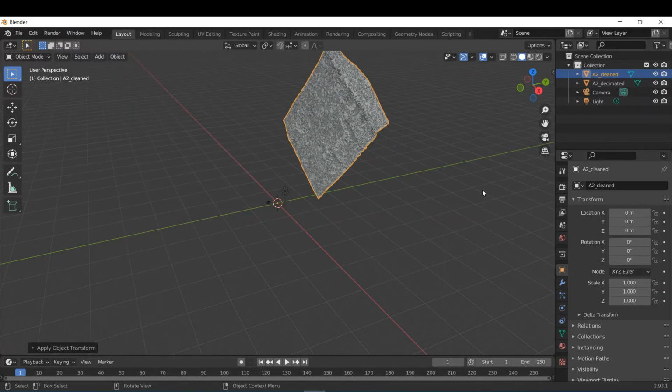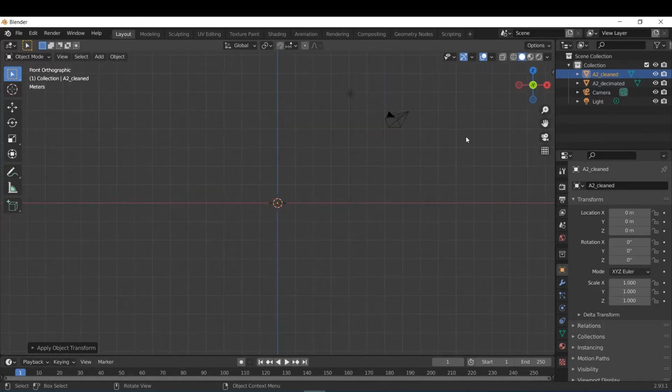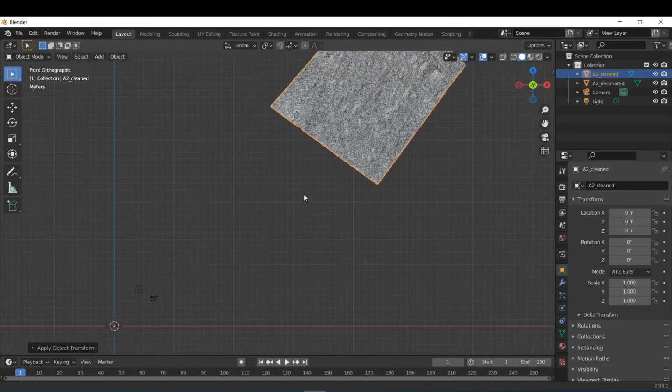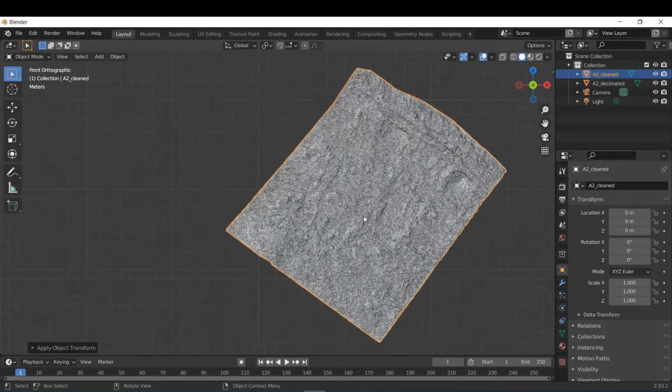So to orient ourselves again, so that things look a bit more familiar, you can click -Y. And to pan, you hold Shift and use your middle mouse button to click down. And so this should look a bit more familiar now. We've got our wall up here, these footings of buildings here.